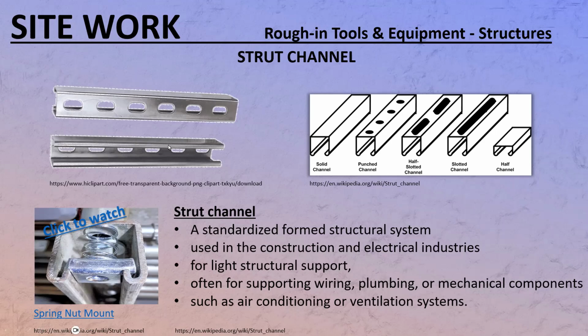If you heat the galvanized steel enough that sparks are coming out, there's going to be smoke, and that smoke contains very toxic fumes. I don't know exactly what's in them, but I was told that we should not be breathing those. Some of those toxic fumes don't kill you right away. They just work in you through the years.